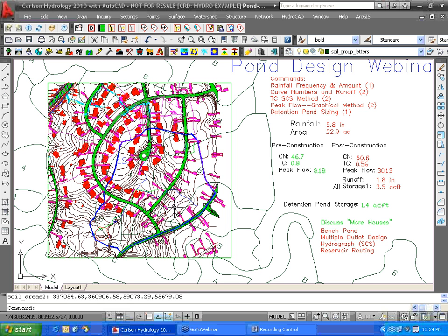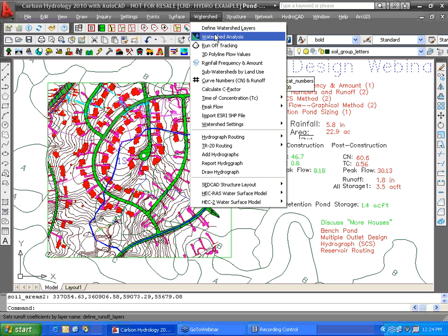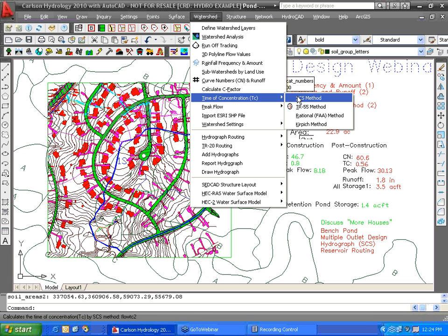Now, the next step is going down the numbers in runoff, both ways, interior pick and where it cuts through everything, soil types and layers. Now we go down to time of concentration, and we do the SCS method. Some people would call this the objective method. There's a lot of subjectivity in the TR55, and Peter has explained to us many times that this was almost a paper and pencil kind of cheat sheet approach before computers allowed the pure objective automation of the SCS method. Let me show you what I mean by the objectivity of this method.